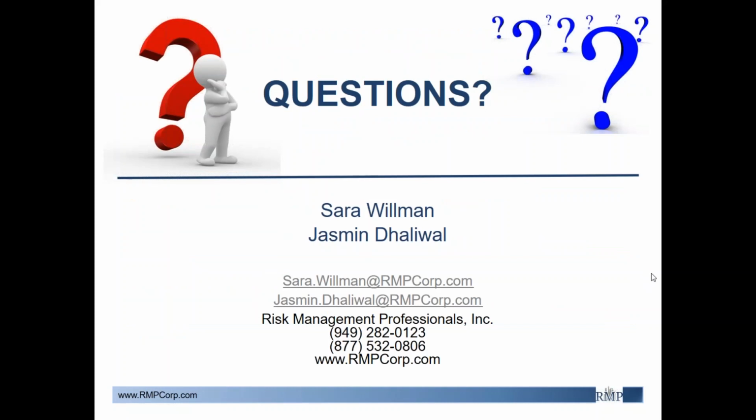Okay, hello everyone. So, first question. Are there any cyclical requirements for HCAs? Yes, that's a good question. So HCAs are required to be performed or updated every 5 years. And that's on top of the requirement if you have an incident at your facility, have an MOC, or perform your PHA, you're supposed to also perform HCAs as part of those instances, as well as doing them every 5 years. So the cyclical requirement is you're supposed to perform HCAs every 5 years.